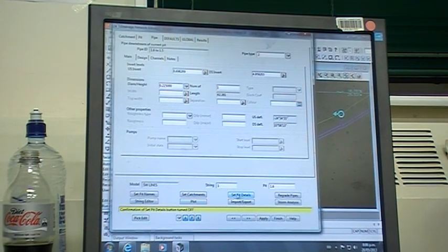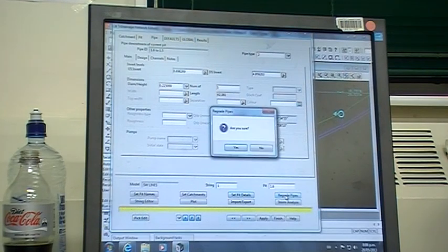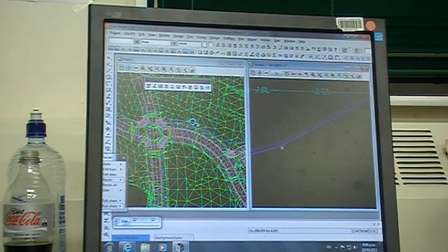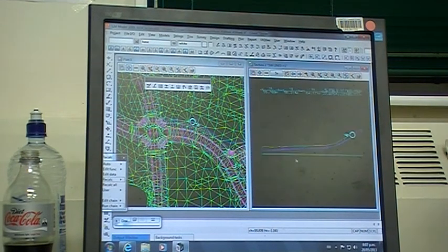So I just right click and turn those little functions off. So I set bit details and then I'll click regrade pipes. If I minimise that now, and again I apologise for this being hard to see at the back, you can see that the pipes upstream are now aligned perfectly using that minimum drop. Previously, some of these pipes were down lower because of the defaults. It's now come up with a solution that meets all the criteria.